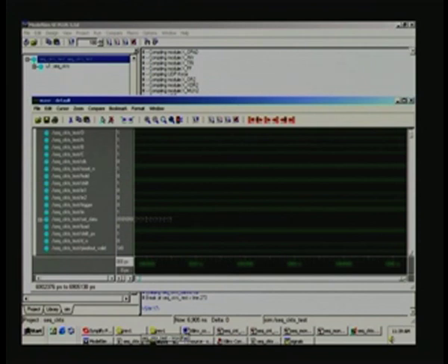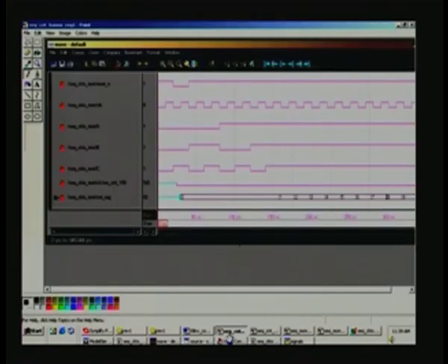So, what we will do is I will directly open some of the examples. I will consider a couple of examples in order to explain the result of back annotation. As I mentioned earlier, the gate delays must manifest here in the waveform, and let us first open what is called sequential counter, which we used for the after optimization. We saw a small delay, and this is what it is. Before zooming in, I will just explain what it is. The whole scene is available in just a single page.